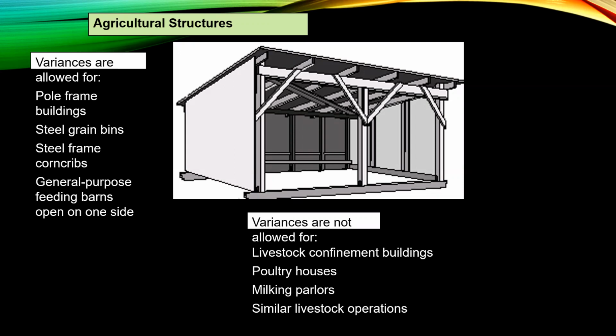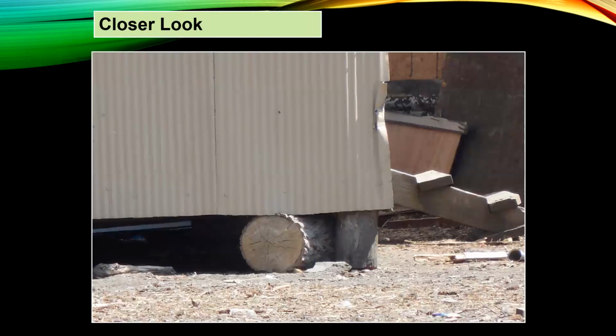So if there's an open wall, as in this structure, so there's no door on that, the entire one side of the building is completely open, we can count that as the flood openings because it's completely open. If there's a door on it, then we can't count it because a door requires human intervention of some kind. So that's not allowed. But if it was completely enclosed, then we'd have to put flood openings in it, and of course be anchored. Elevate utilities, have flood-proof materials below the base flood elevation, and all the same requirements as wet floodproofing the accessory structure.